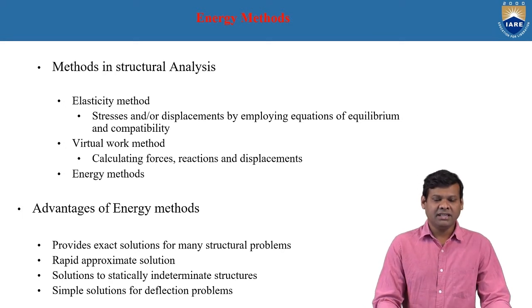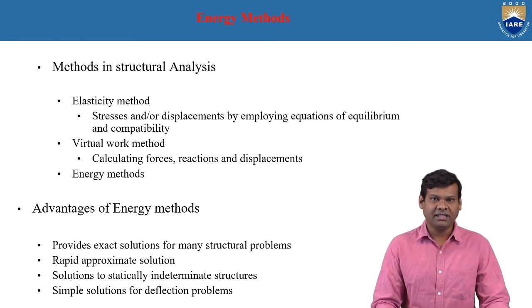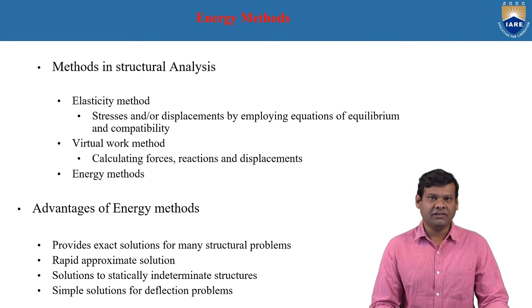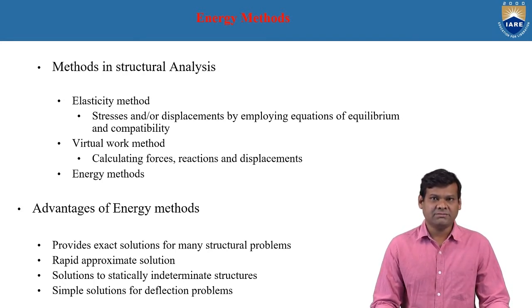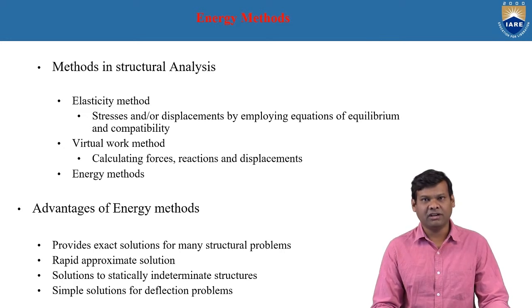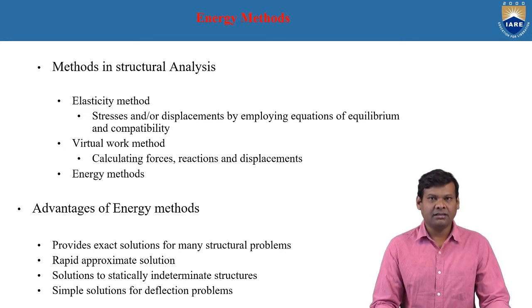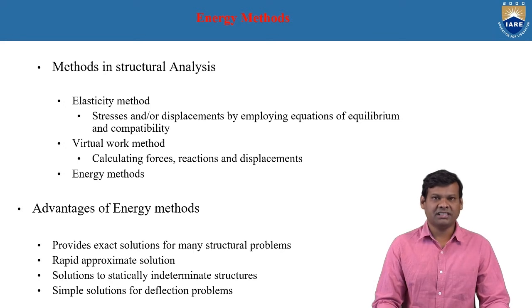In the elastic method, the stress or displacement are calculated by employing the equations of equilibrium and compatibility. That is, by using the equilibrium and compatibility conditions, what we deduce by applying this elastic method is the stress or displacements. Next is the virtual work method, which relies on the principle of superposition, and this is helpful in calculating the force, reaction and displacement in a structural system.